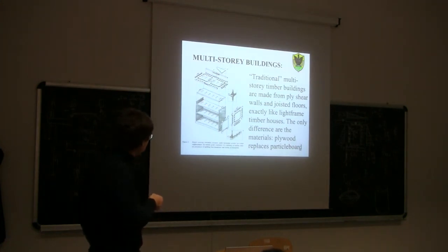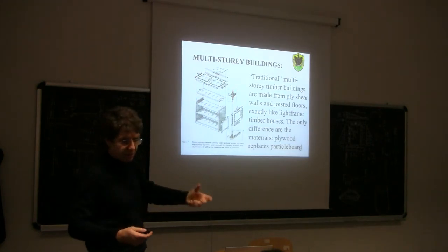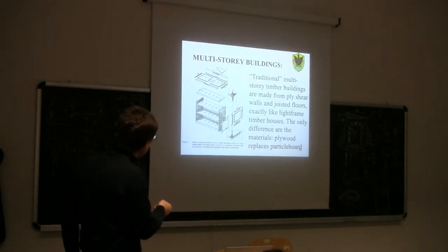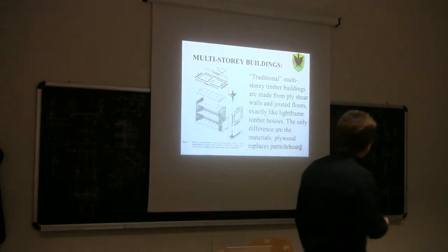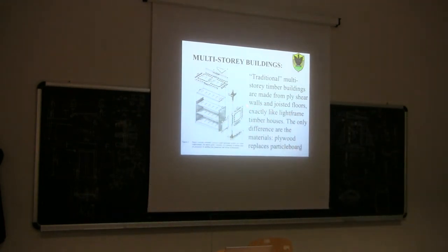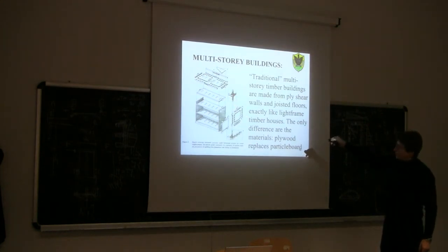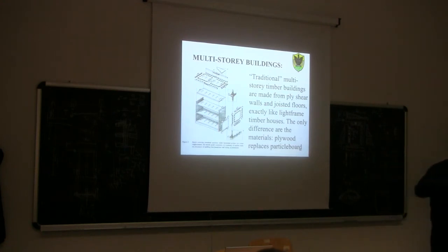This continuity is usually provided by steel straps connecting with nails the upper stud with the lower stud through the floor. As you can see, this is a kind of platform construction because there is a discontinuity on the floor. So on the floor, you see the stud is connected to the floor and then the next stud is connected to the top of the floor. So this is again what is called platform construction. It's not the best one in terms of static resistance because of course you have timber loaded perpendicular to the grain, but it's the best one in terms of constructability of the structure.